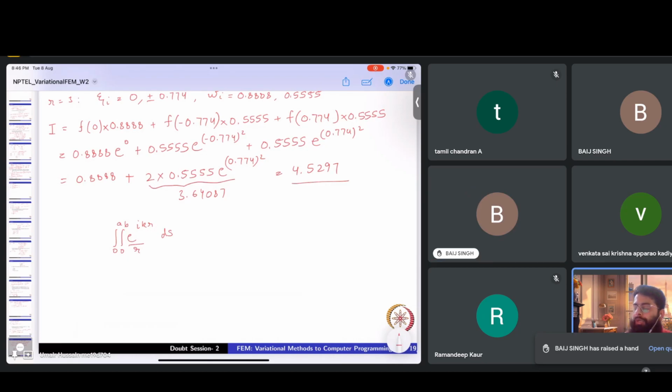And earlier, sir, you had asked about reduced integration or reduced elements, reduced integration points. Generally, we say that suppose we don't use Gauss points. In that case, you have to use complete elements, with all the nodes considered. But when we use C3D8R or S4R, then we have to consider only the Gauss points or integration points.